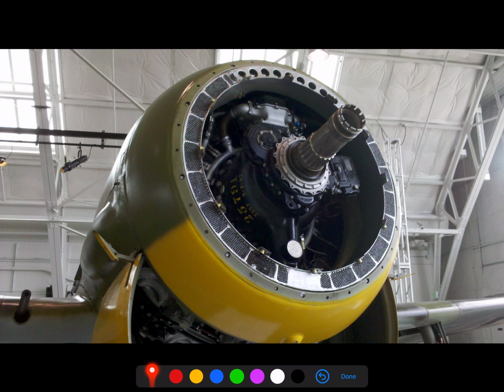When we have a liquid-cooled engine, we have engine coolant that circulates through and takes that heat away from particularly hot areas like the cylinders and cylinder head and moves it out to a radiator where it can exchange that heat. In the case of an air-cooled engine, we use lubricating oil, which can absorb that heat through contact with critical components inside the engine and take it out to an oil cooler where it can exchange that heat with airflow, very, very similarly to the way that a liquid-cooled radiator would.